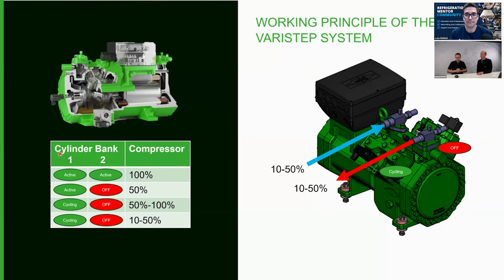So therefore, we increase the speed or the capacity of the compressor, and then the rack controller identifies, I have too much capacity in the system. I need to stop either this compressor, if it's the only one which is active, or if we have a compound system, it stops compressor number 2. Compressor number 1 will automatically run then at 80, 90, or 100% and gets the full mass flow, is cooling down again. Everything is fine. We don't create any alarm or any unnecessary stop of the compressor. We brought the compressor out of that critical situation without making any trouble, let's say.